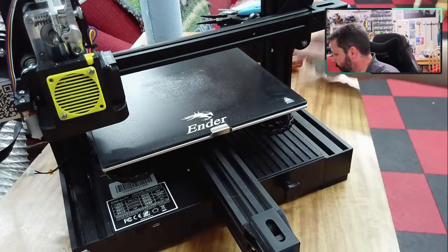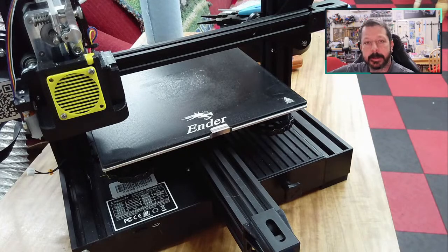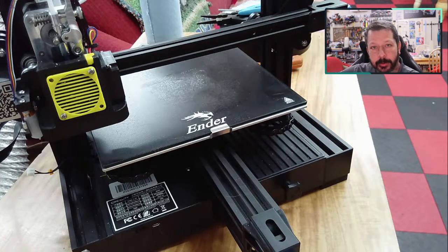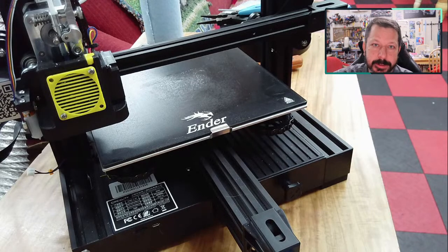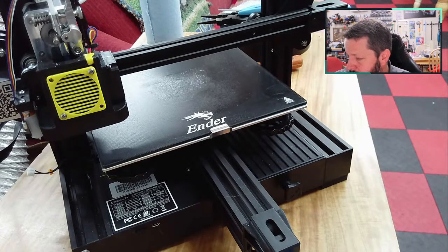I don't have one here, but the intake manifold was so thin that in the orientation I had, it was thinner than the minimum layer thickness that I was doing. So it just didn't print those parts because they didn't exist as far as it was concerned.